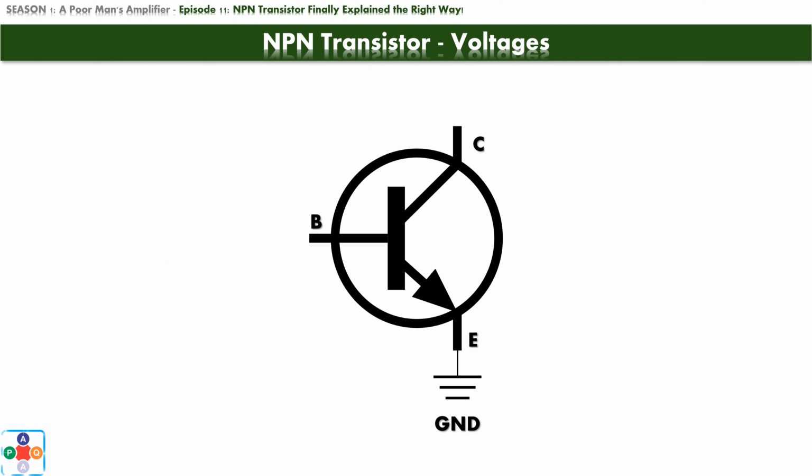Now, depending on your circuit design, you can have multiple resistors, multiple capacitors, even diodes, and whatnot, in your transistor circuit. It is very important to name all the nodes in the circuit, or simply set every connection point between different electronic components, and name voltages and currents accordingly. This is a mark of the professional.